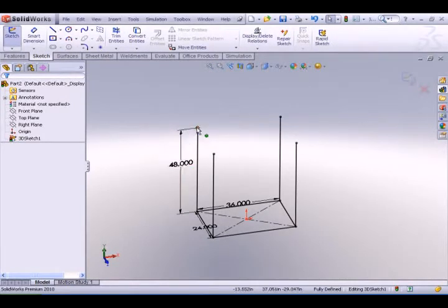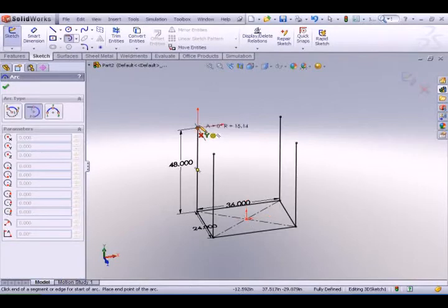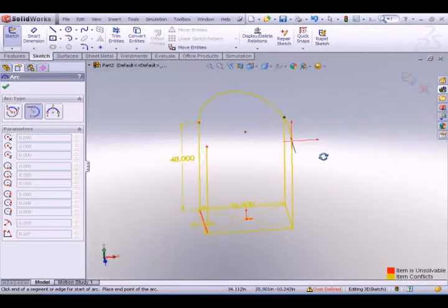All right, so the next thing I'm going to do is I'm going to need a tangent arc to go across here. The nice thing is a tangent arc in 3D space works very well. And even if I'm in the wrong plane, notice this is drawing along the back wall. If you come up next to a point, it will automatically snap and put in that 3D point.